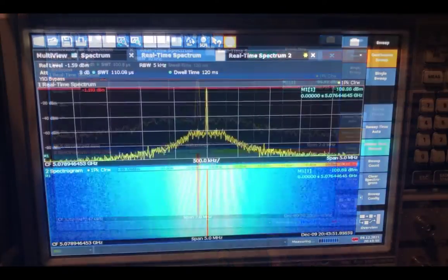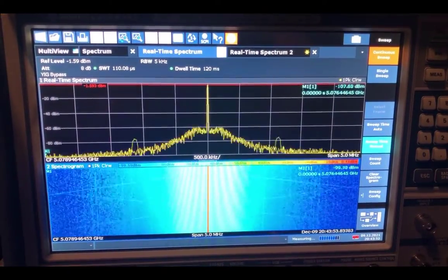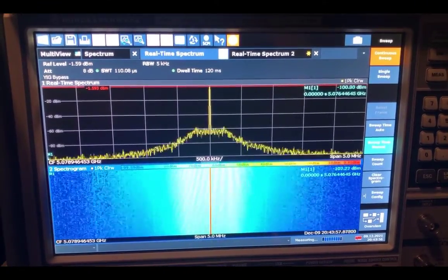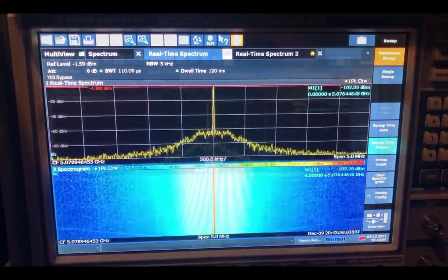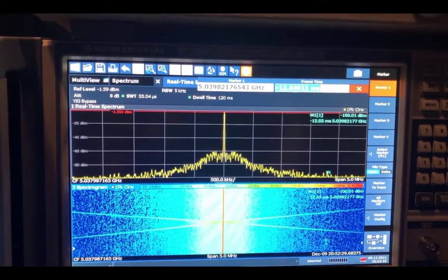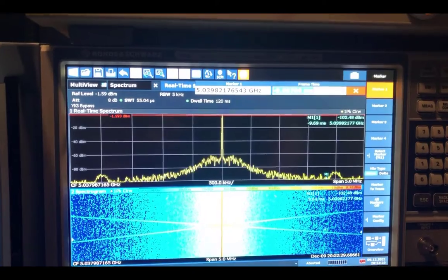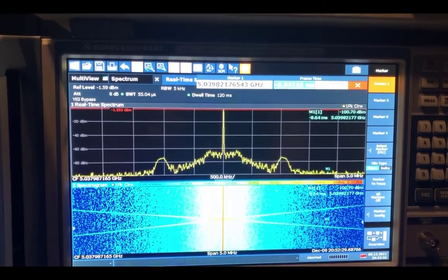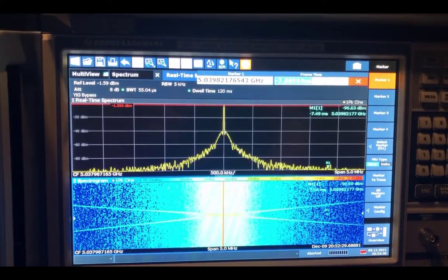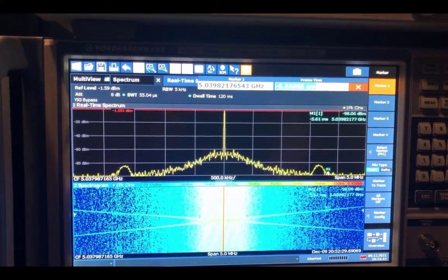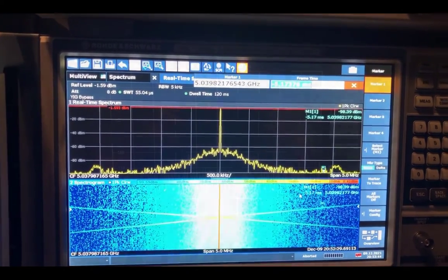In the spectrogram, the carrier, which is fixed in frequency, appears as a vertical line. Wandering spurs, which move towards and away from the carrier, appear as two V's that meet at their tips. As time advances, the two wandering spurs move linearly in frequency towards the tip of the V at the carrier and then away from it. This gives the wandering spur spectrogram its characteristic tip-to-tip V shape.